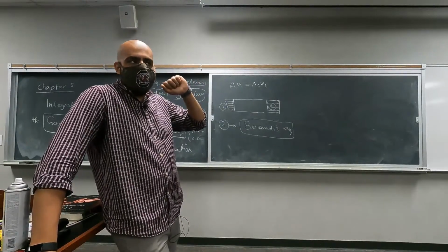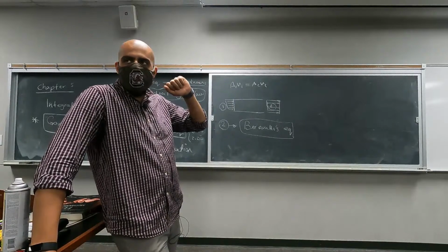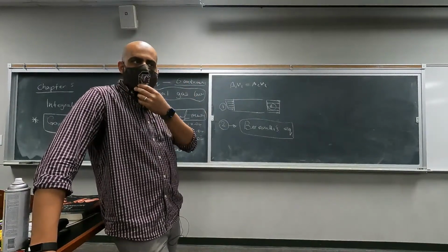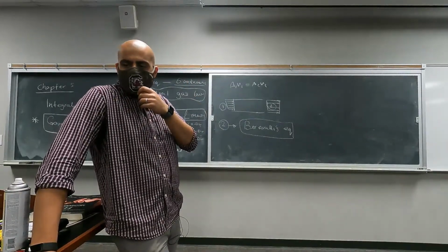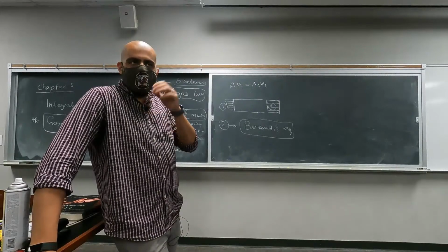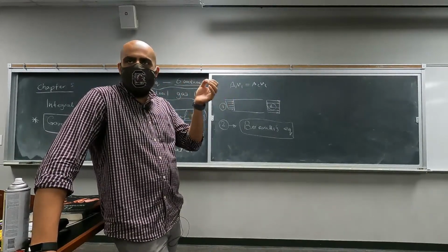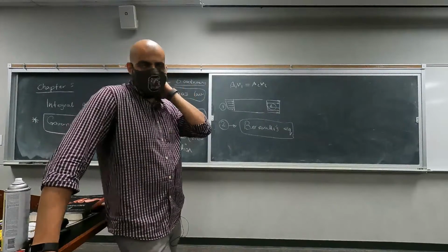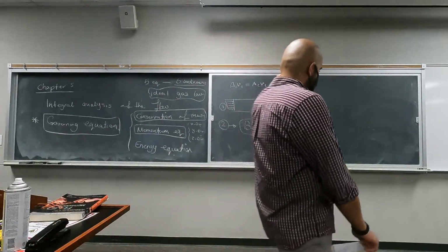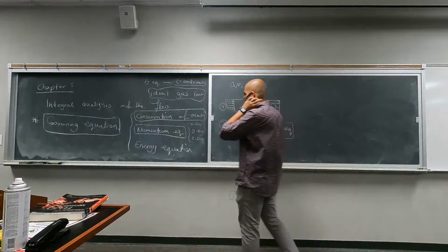Does anyone remember? No one? Incompressible, along a streamline, inviscid, and steady state, right? These were the 4 assumptions that we needed to make to come up with Bernoulli's equation.